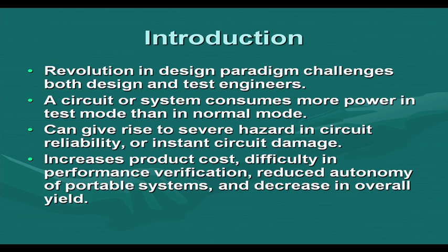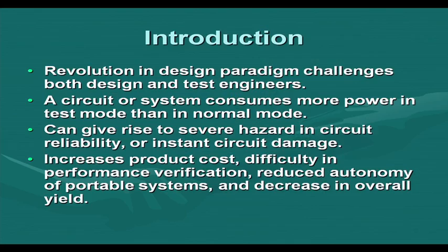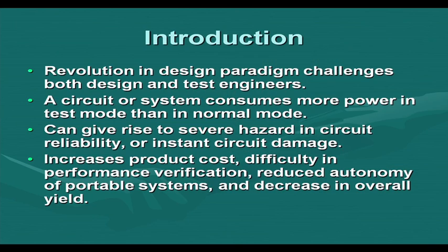Performance verification is a problem, because again the same thing, power-aware operation has to come into the picture. Portability will reduce, because the circuit has to be a battery-operated circuit if it has to be tested periodically, and if the test power consumption is high, then the battery life is in question. So, this autonomy of portable systems becomes less, and as a result there will be a decrease in the overall yield.